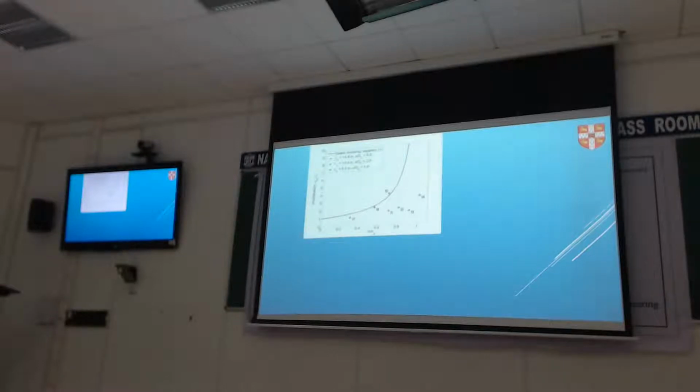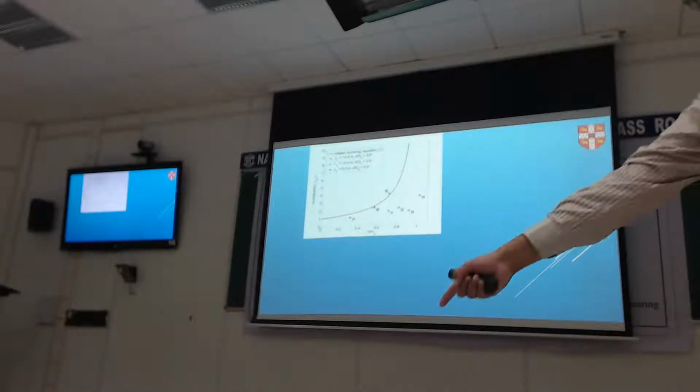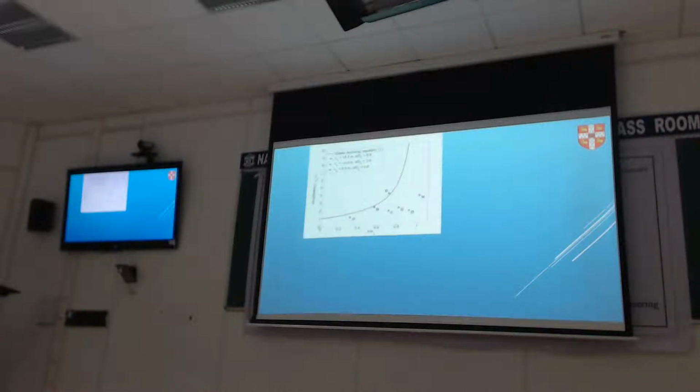So that's that axis. This is the load we applied relative to Euler. Notice that there's just one experiment close to the Euler load. Everything else is under the Euler load, because to apply the Euler load and make the thing stand at 60G or 80G, whatever G level we did, is quite difficult, because we also can't make piles perfectly. So we will have our own imperfections and load misalignment even in a centrifuge. So we only ever dared go all the way to the Euler load on one experiment, because it's so easy to lose the experiment. If you put too much load, it will buckle easily.